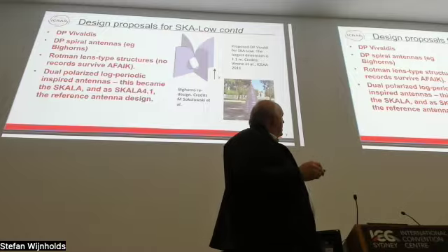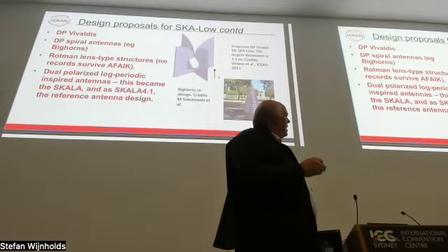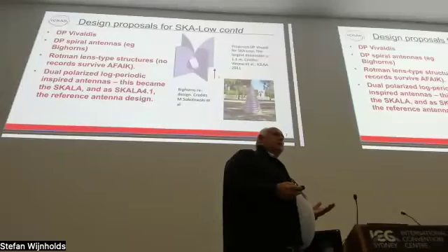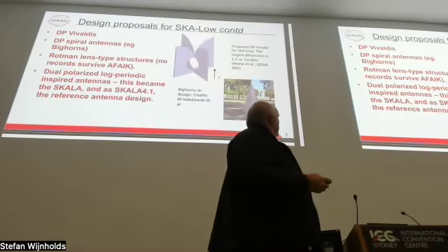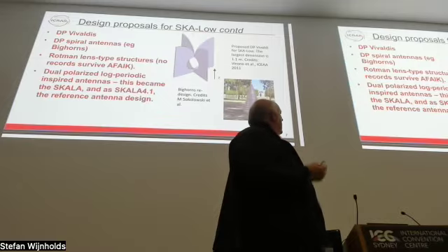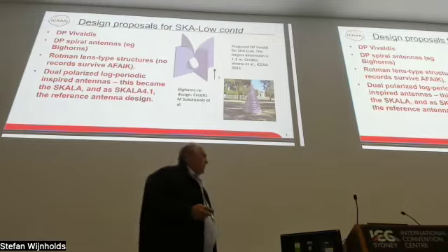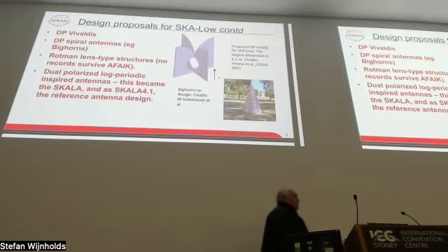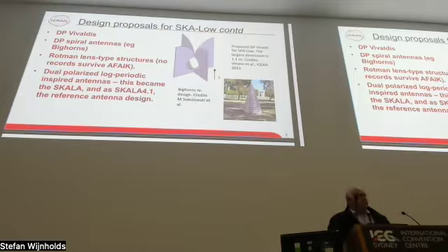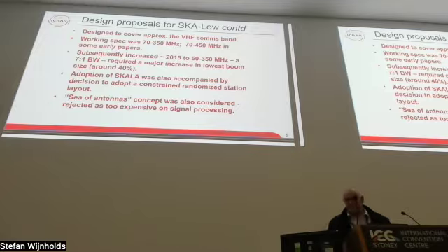Here's another idea. This is the Bighorn design, which Martin Sokolowski at ICRA developed. Essentially, it's a log periodic, it's a 3D equiangular antenna. Again, you can see there are some production issues with these, although whether they're any more serious than the production issues of the dual polarized log periodic, I'm not sure. Somewhere around 2011 and 2012, the Scala antenna became kind of the design reference, and nobody went back and looked again at the antenna design after that.